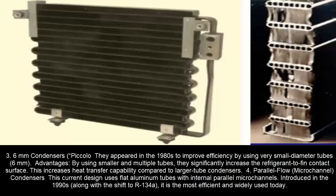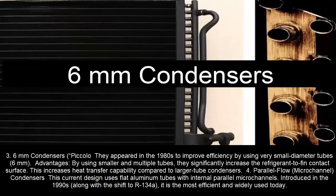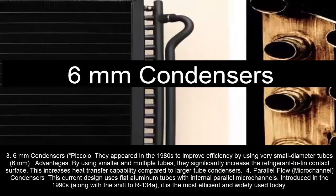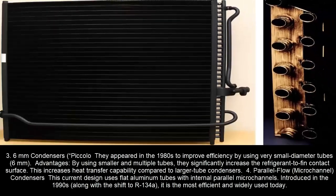3. 6mm condensers, or piccolo. They appeared in the 1980s to improve efficiency by using very small diameter tubes, or 6mm. Advantages: by using smaller and multiple tubes, they significantly increase the refrigerant-to-fin contact surface. This increases heat transfer capability compared to larger tube condensers.